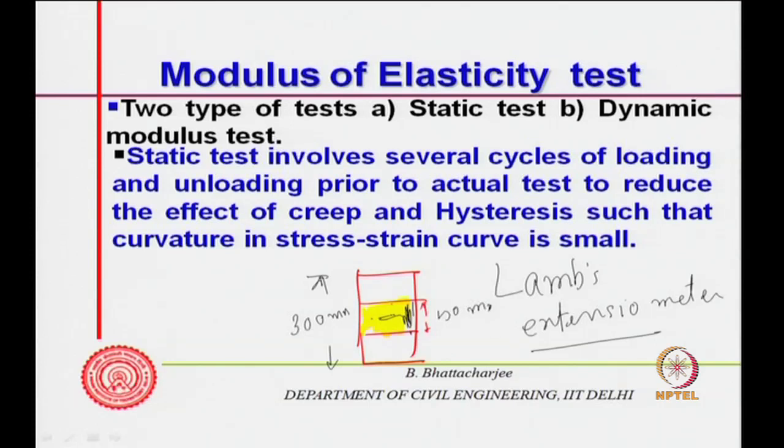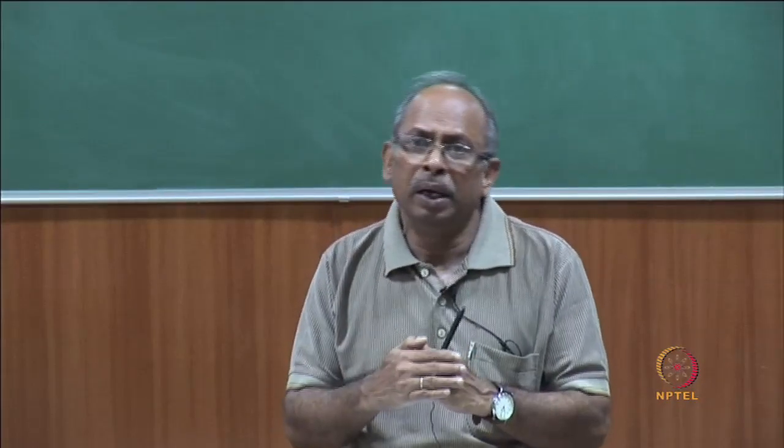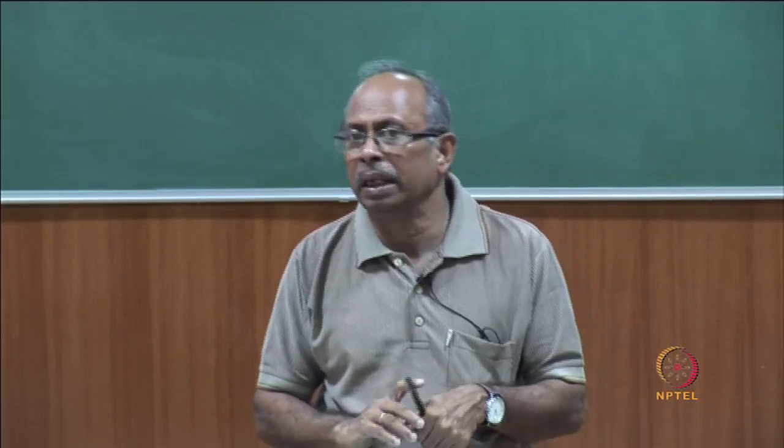within the small range. But before doing that, you crush a cylinder to find out the cylinder failure strength, FCYL, and then load up to 1/3 of FCYL, that is the cylinder strength, and then unload it. These cycles were repeated to see, first of all, that there will be no deformation right in the beginning because of the plate settling down and things like that, number one.